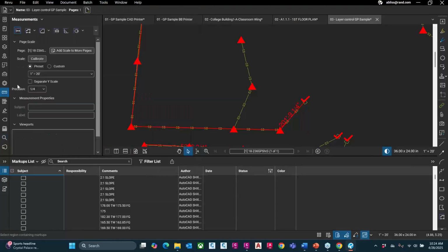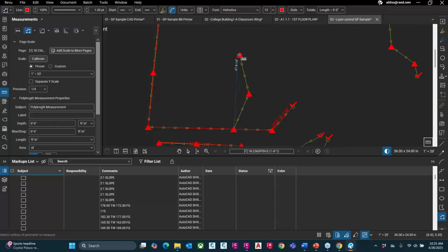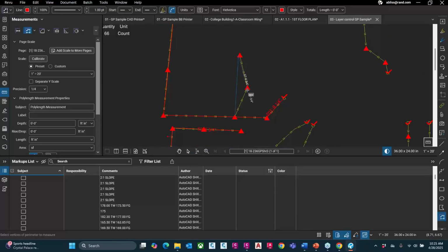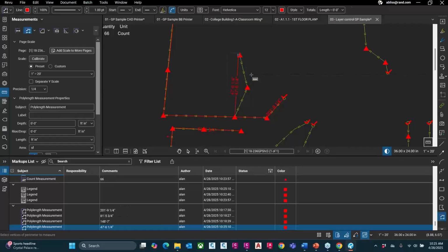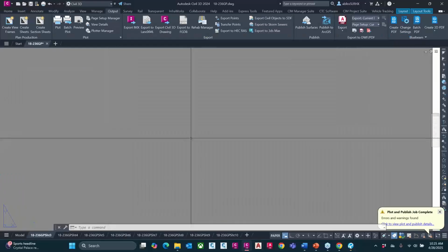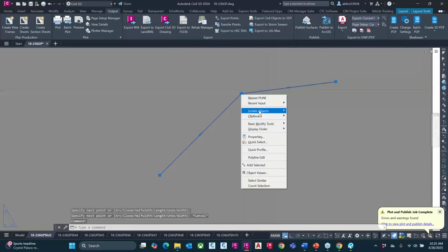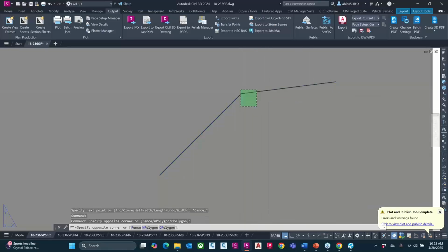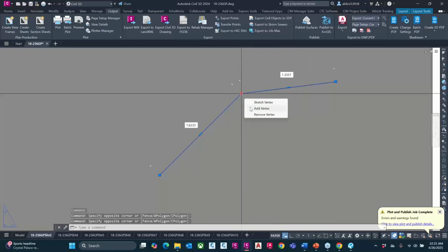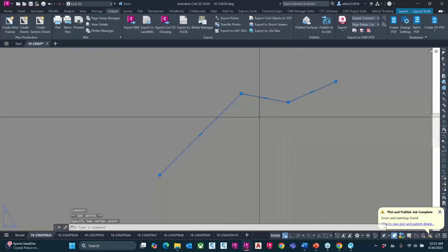I'm going to make a measurement. Let me go over here. I'll do my poly, and I'm going to measure from endpoint there to endpoint of that line there. All right. So just like in AutoCAD or Civil 3D, hey, we got it open, might as well go over there. I do a polyline, and I can add a vertex when I hover. Vertice is plural, vertex, add the vertex. Try to sound fancy and just shoot myself in the foot. Add the vertex, and then you can add as many vertices as you want.